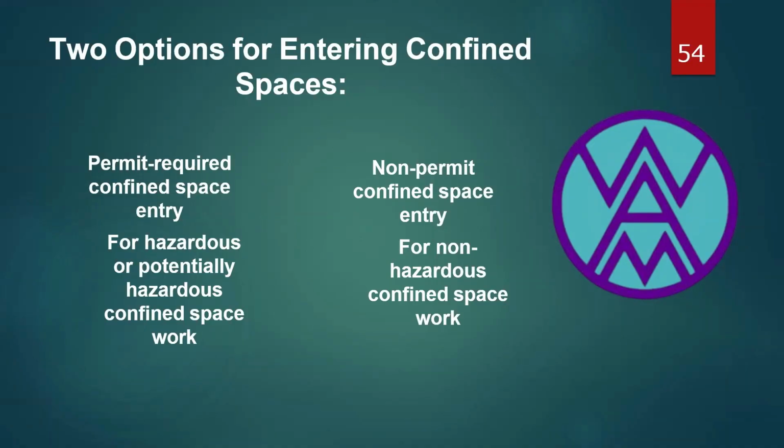That's kind of good, but let me explain it more to you. Let's suppose a person is working inside a confined space and he is performing a hot job, like welding. So does he only need a confined space permit, or does he need both permits, the hot one as well? I did not get it. Okay, let me say it again. If a person is working inside a confined space and he's performing a hot job, how many permits will he require here? I'm not sure, but let me say two. Yeah, he will use both permits. He will use the permit for the hot job as well as for the confined space, because both of these things pose their own risks and their own hazards.